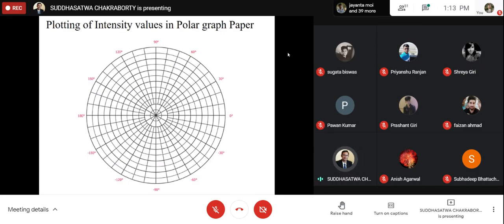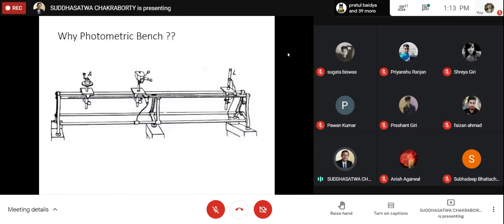So in our case, whatever measured data we are taking, run 2 is much simpler. You already have calibrated, so in run 2, I'll be fixing up my test lamp for which we are supposed to measure the luminous intensity. I'll be fixing it up here, and at a particular distance, maintaining the point source realization, I'll be fixing my test lux meter with a proper calibration, because run 1 will give me the calibrated data. I will make all possible corrections. Now, what do I need to do to measure the intensity value?